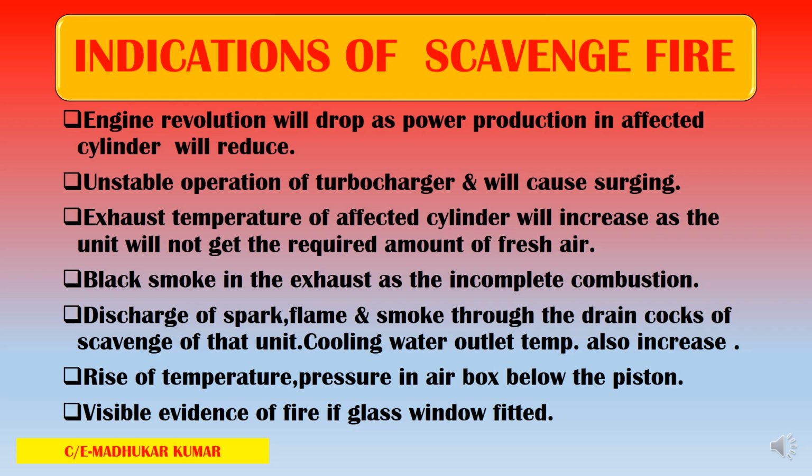Okay, so this is also one of the things. Exhaust temperature of the affected cylinder will increase. If the scavenge temperature is going to increase, this is also going to increase as the unit will not get the required amount of fresh air. The fresh air amount will reduce because there is already a fire in the scavenge space of that particular unit. So this is also an indication, and the temperature of that particular scavenge space unit is increased.